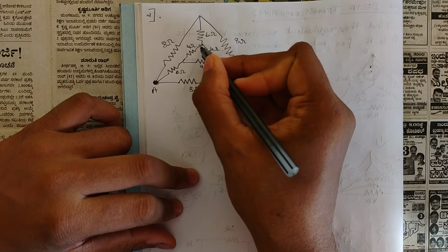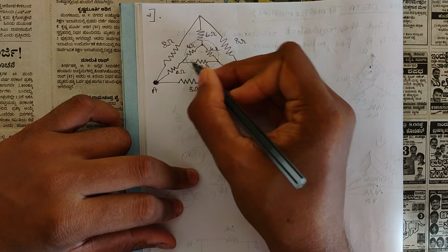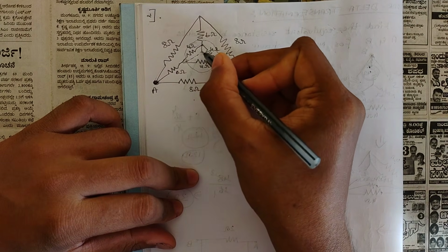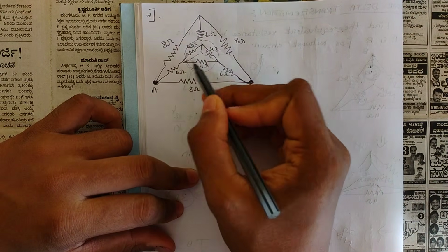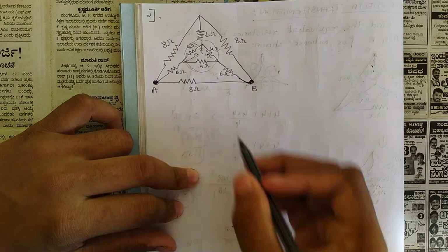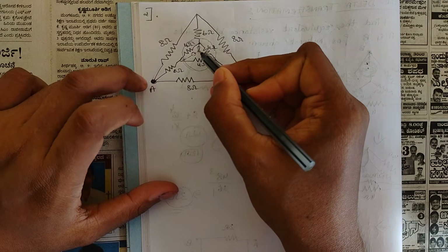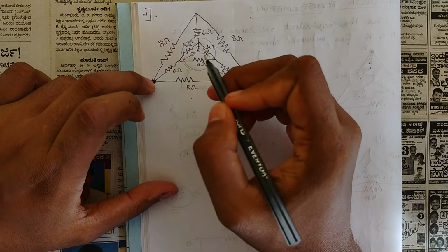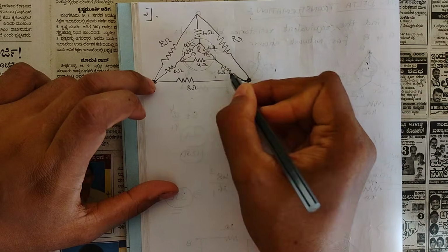this is very simple. First consider this internal delta connection here. Convert this delta to star, like I have written in dotted lines here. After we convert this delta to star, we would have 3 resistances here. After the conversion of delta to star, from this point to this point we have 2 resistances in series. We can add them and make it a single resistance. Similarly here we would have 2, and here also we would have 2 resistances